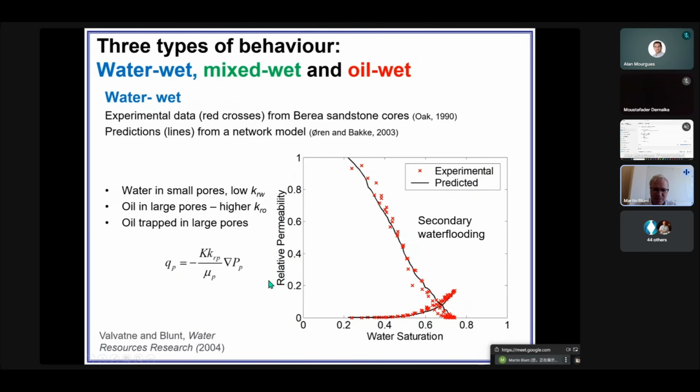So here is the relative permeability as a function of saturation. Most people find it necessary to label each of these curves. Hopefully it should be obvious that this is the water relative permeability because it's increasing with water saturation, and this is the oil relative permeability because it's decreasing, because the oil saturation is going down. This is a water flood relative permeability. So the saturation is going from about 20%. That's the initial saturation. In this particular sandstone, there's quite a lot of clay, so it's basically clay-filled, low permeability regions. And then we go here and we see that we leave behind a residual saturation of about 30%.